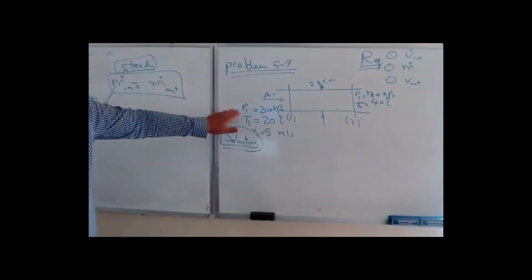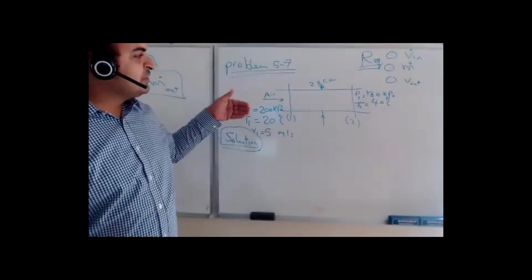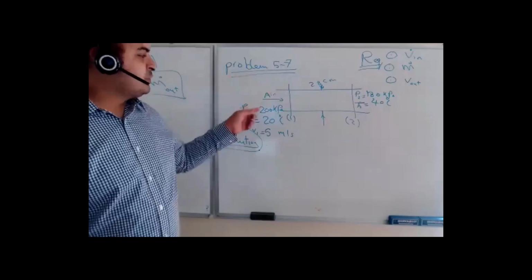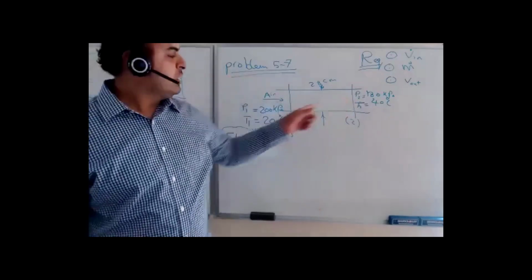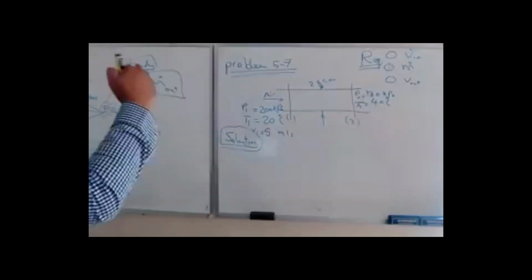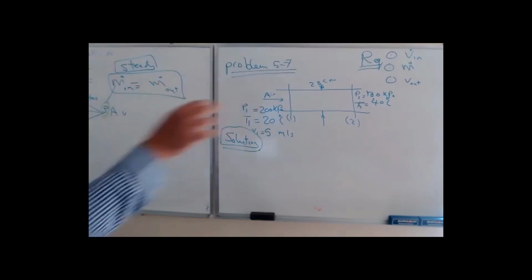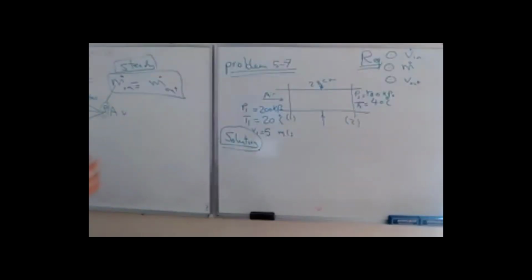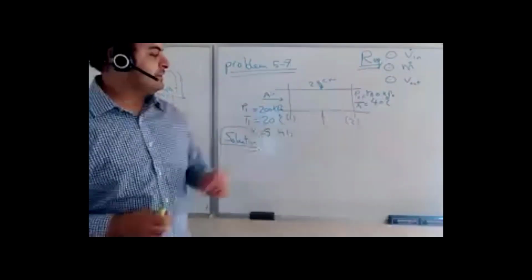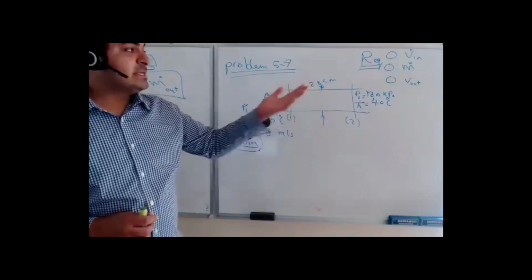So here was 200. Of course, here is lower, 180, because this is the flow direction. This is called pressure gradient. Flow is driven by pressure, so flow goes from high pressure to low pressure, 200 to 180 kilopascal. We have a negative pressure gradient, pressure decreasing, which drives the flow in this tube. Fluid mechanics problem. The air is moving, but temperature also increases from 20 to 40.